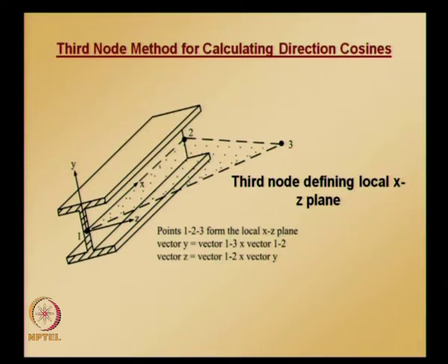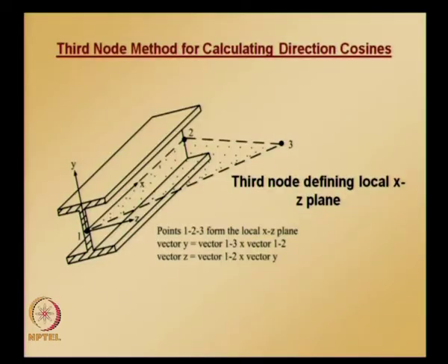We need to convert back into the displacements in the local coordinate system, because using this we will be calculating axial forces, moments and shears, or even displacement at any point along the frame element. For an element with a uniform load Qy, Qz, Qy in the xy plane, Qz in the xz plane, the equations in terms of local coordinates, that is s is equal to 0 corresponds to node 1, s is equal to 1 corresponds to node 2.